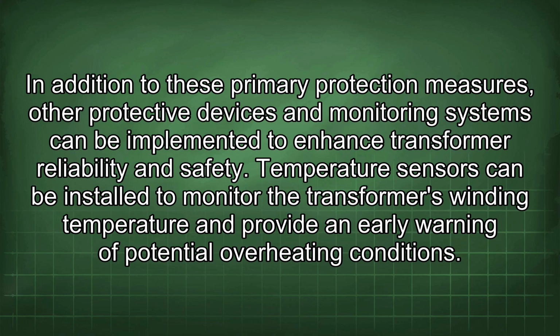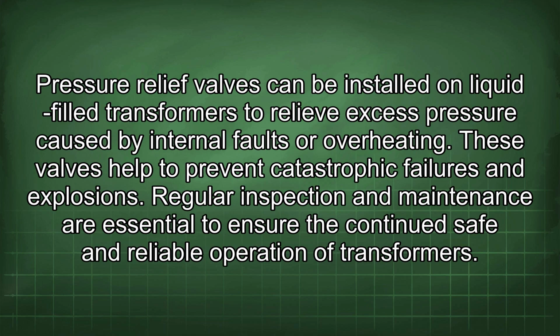Temperature sensors can be installed to monitor the transformer's winding temperature and provide an early warning of potential overheating conditions. Pressure relief valves can be installed on liquid-filled transformers to relieve excess pressure caused by internal faults or overheating. These valves help to prevent catastrophic failures and explosions.